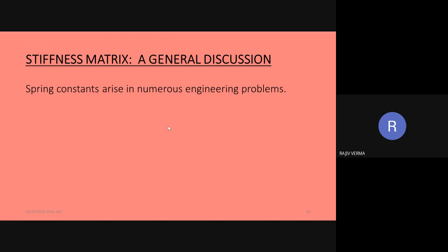So if you interpret this with respect to the spring which we have just discussed, nodal degrees of freedom obviously mean deformation or displacement, and the corresponding disturbing parameters acting on the nodes represent forces. So in the present example, the stiffness matrix represents a mathematical relationship between displacements and forces.